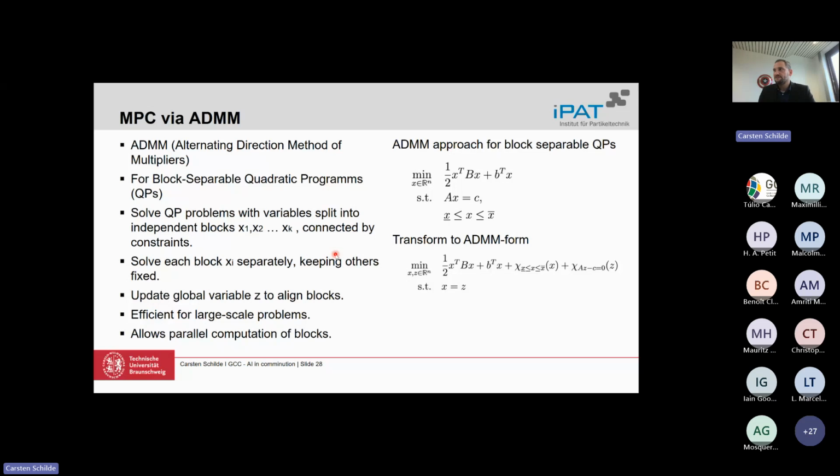And why is this necessary? This is necessary in order to be fast. We need to have a process control which is very fast, and bringing it down to easier subtasks with only one parameter dependency, and then putting everything together on a larger scale is much faster than trying to solve the whole population balance model online.